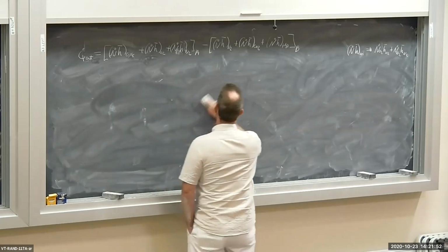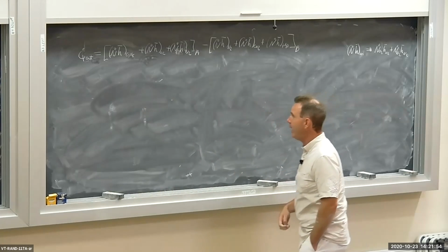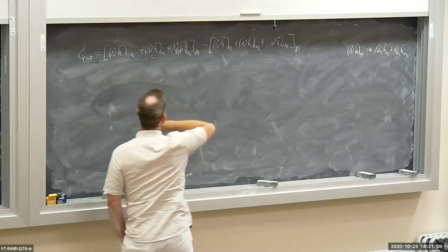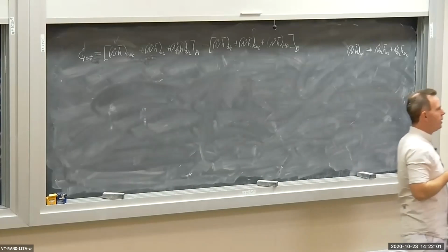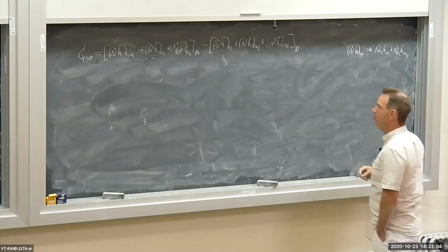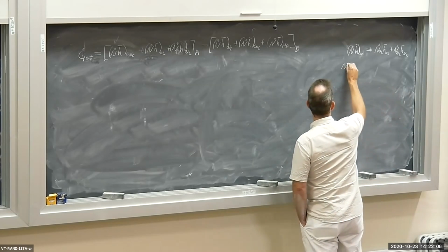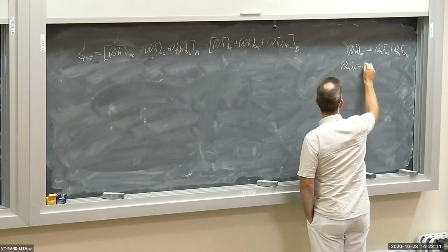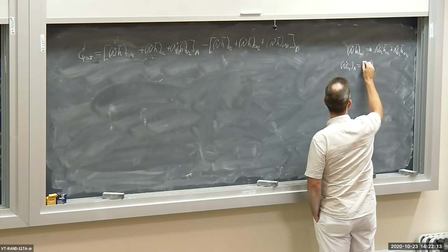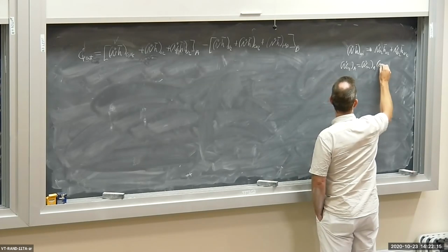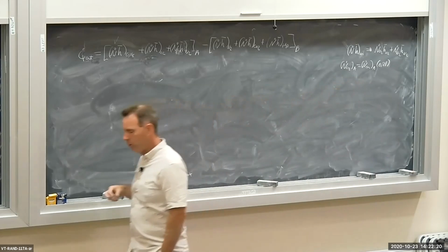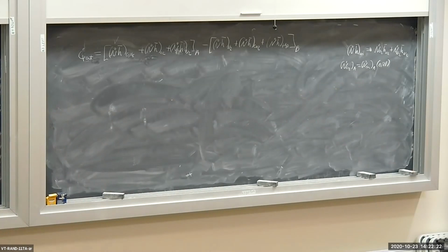Now let's see what we got here. I have the N dot for the fuel, the N dot for the oxygen at the inlet. N dot O2 at the inlet is equal to N dot for the air at the inlet times 0.21, so it's 21% oxygen.